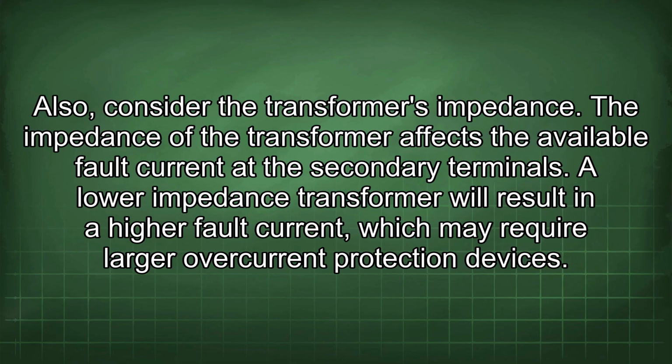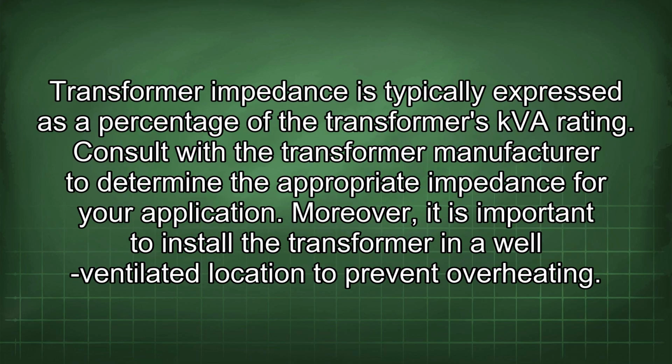The impedance of the transformer affects the available fault current at the secondary terminals. A lower impedance transformer will result in a higher fault current, which may require larger overcurrent protection devices. Transformer impedance is typically expressed as a percentage of the transformer's kVA rating. Consult with the transformer manufacturer to determine the appropriate impedance for your application.